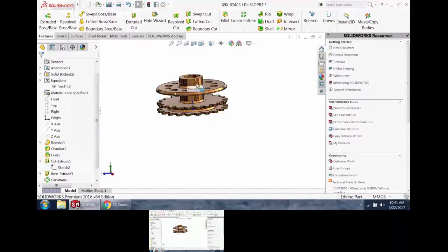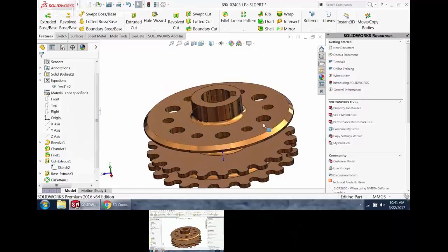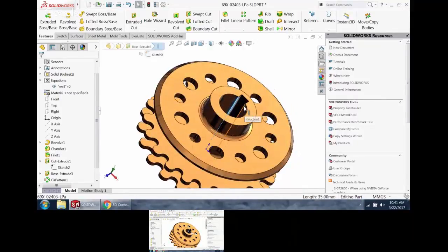I use the measure tool only for really complex measurements. For simple measurements, if I pick a circle, right down here it lists where the center of that circle is and what the diameter is. If I pick an edge, that's how long that edge is. So you don't even really need to go into the measure tool for most of your measurements. If I control select and pick another edge, there's the distance between those. It does top off at a point where if you pick 3 items, it's going to have no idea what you're asking for. But if you pick 2 faces, it's going to say, oh, here's the distance between those 2 faces. It'll figure out from your selection what measurement you're after. So here with the 2 lines, you see that it told me what the 2 lines' total distance is, as well as the distance between them.